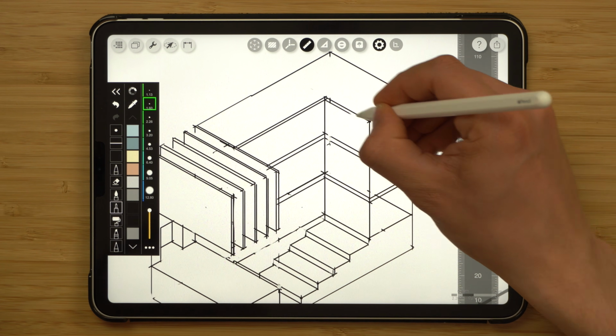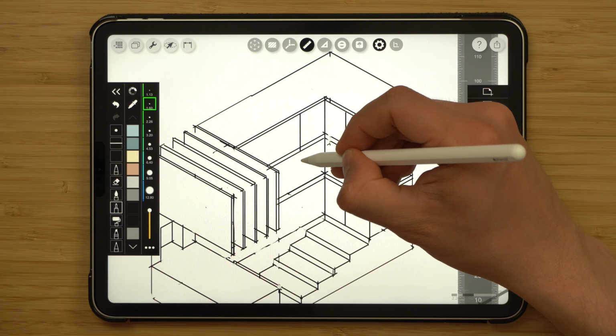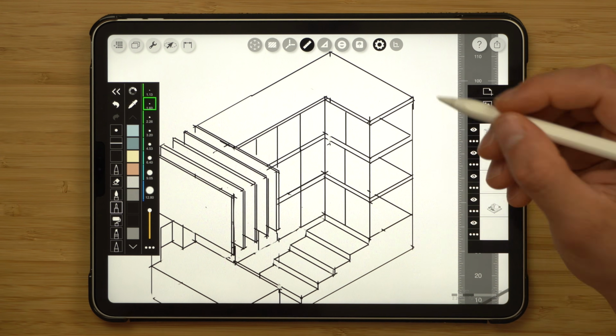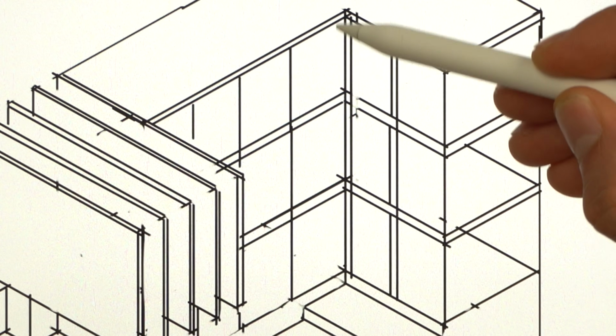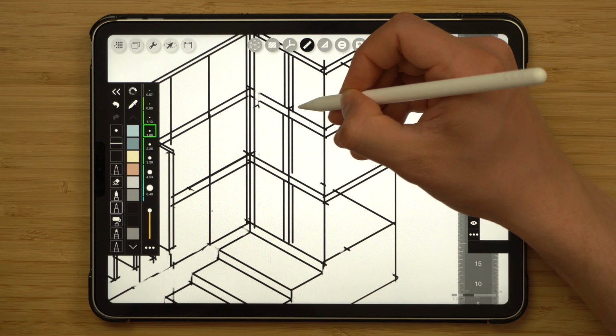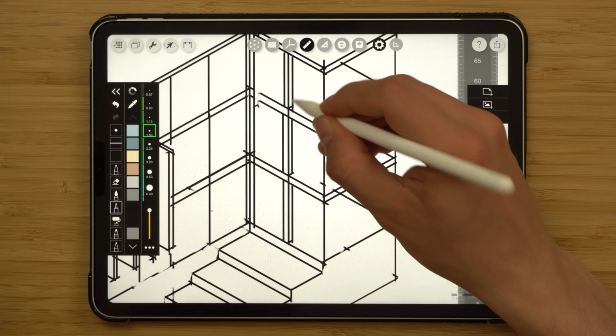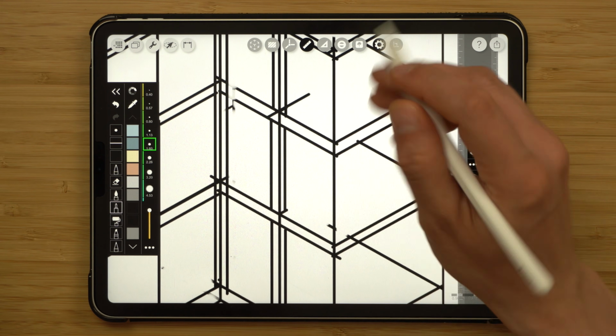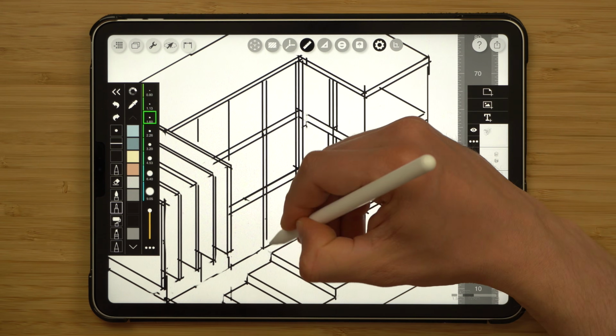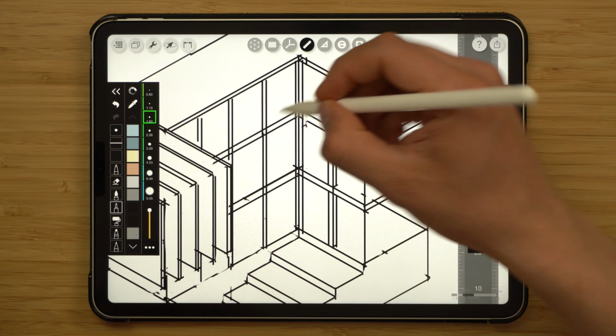Before I do that, I'll just add thickness to that last balcony, and then, more as we did before, show a couple of divisions and then add thickness to those. You know, this first side is flush, but then these columns will actually have a depth, and that's why I have 3 lines. And then that line at the base is kind of diagonal, like so, just to portray the illusion of the thickness and the structure being there.